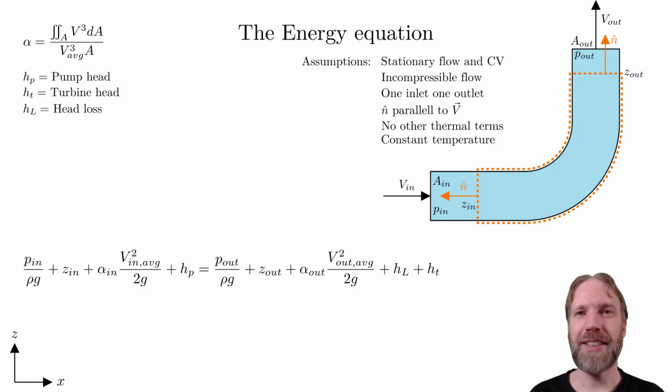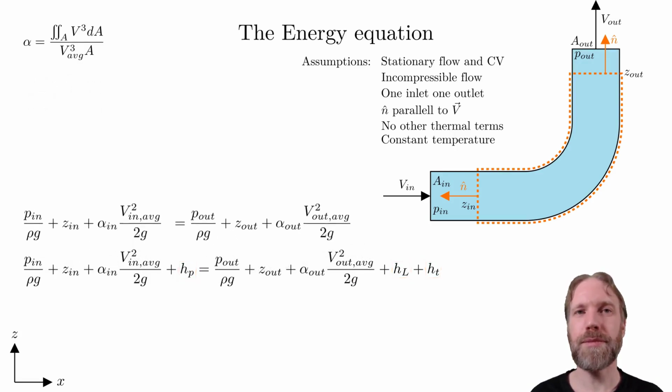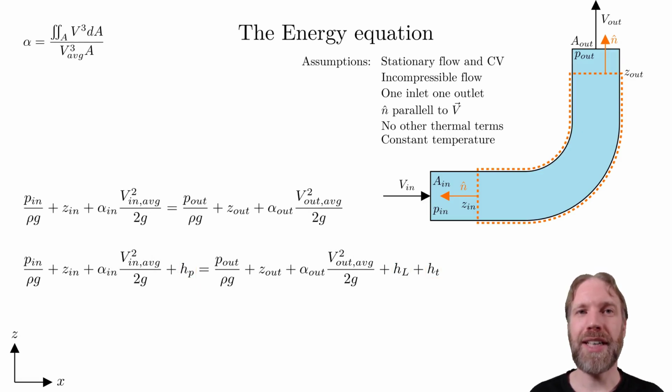From the energy equation, we can derive the Bernoulli equation. This is basically a simplified version of the energy equation. First, neglect the pump, the turbine, and all losses. Now, introduce a streamline into the pipe. For simplicity, we assume that the center line is a streamline. A streamline indicates the direction of the flow. Hence, a fluid particle should travel along this streamline.